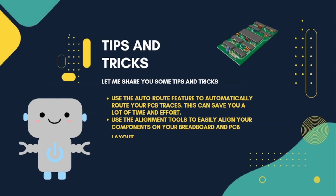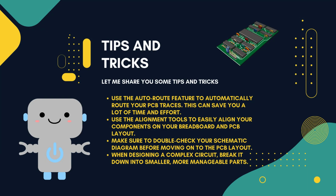Now let me share some tips and tricks. Use the auto route feature to automatically route your PCB traces. This can save you a lot of time and effort. Use the alignment tools to easily align your components on your breadboard and PCB layout. Make sure to double check your schematic diagram before moving on to the PCB layout. When designing a complex circuit, break it down into smaller, more manageable parts.